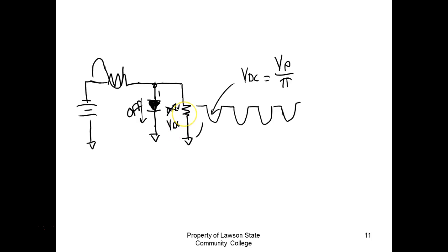You understand? Well, that's not true. So we need to think about this. So if this is a 1K, and this is a 1K, and this DC is 10 volts, then what I would get over here is 5 volts. So that's something that I forgot about. So what we showed you a while ago wouldn't be quite right.